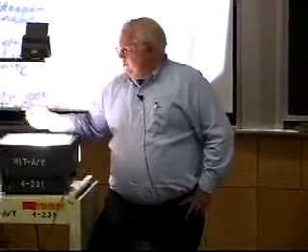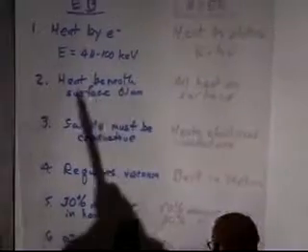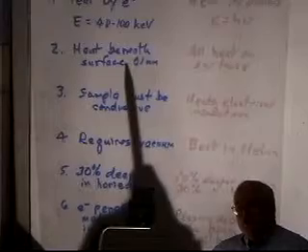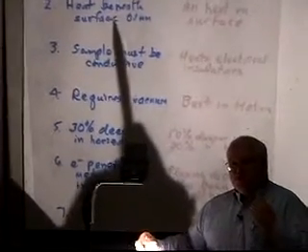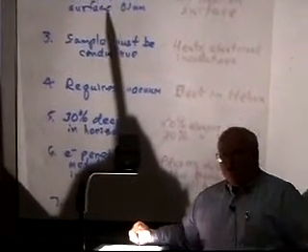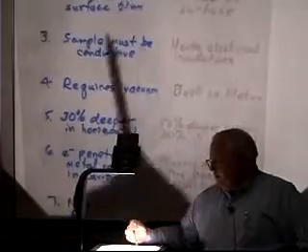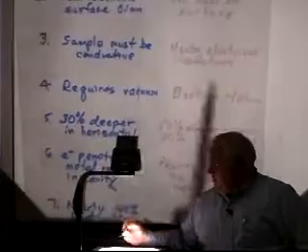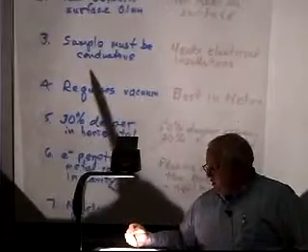But anyway, so these things have high energies, and they will penetrate through. Over here, they don't have high energies, and they don't penetrate through. Here, you actually heat beneath the surface, and you get favorable surface compressive stresses. And so you wouldn't get fatigue cracks on those surfaces. Okay? So there is a difference. And so they actually did make it work with electron beam.